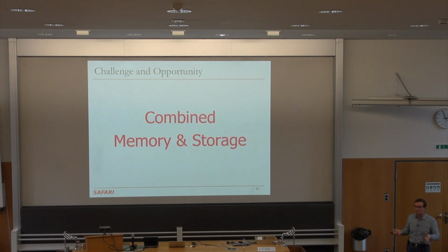Okay, so a huge challenge and opportunity, especially with these new technologies, is combining memory and storage. There are efforts in flash. Flash is interesting because people are trying to design very low latency flash today. I think Samsung has a Z-NAND or something like that. They have fast devices that they're trying to put out. Fundamentally, flash is not as fast as something like STT-MRAM, for example, but clearly those fast flash devices can close the gap between DRAM and existing flash devices.